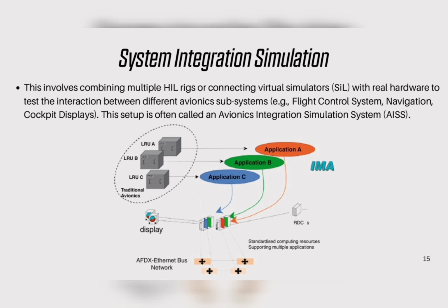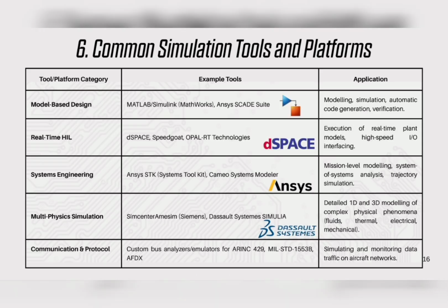Validation confirms the system meets operational needs. Scenario-based testing, HIL runs, and ultimately flight tests with instrumentation to capture system behavior in real operations. Common simulation methodologies include the MBD workflow I described, plus SIL, PIL, and HIL. Tools used in industry reflect these needs.